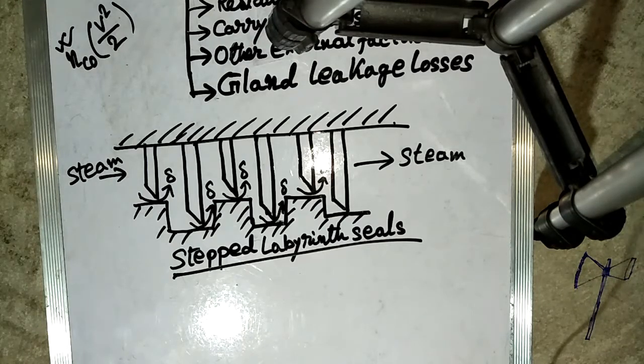Okay, it is necessary to use shields or packing to further reduce the leakage flow. These shields may be labyrinths, carbon rings, water or steam seals, or gland leak off. To prevent the shaft leakage, the labyrinth may be used with carbon rings and gland leak off. The labyrinth seals consist of various thin strips fixed with the casing which maintain the smallest possible clearance with the shaft, as shown in this figure.